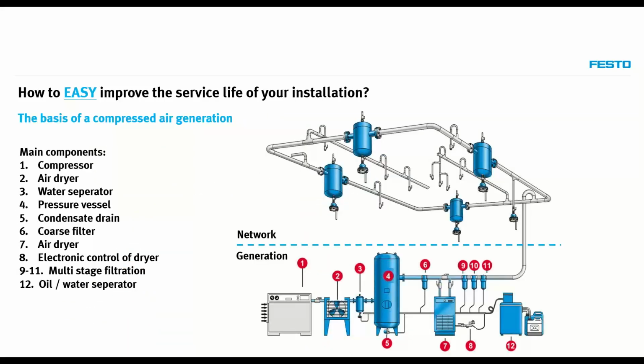So in general, what are the basic components of a compressed air system? For this, we would like to zoom out on the entire system itself, because many times people are only looking at a compressor, or only at the pressure vessel, or the air grid which is available. But at the end of the day, it's a system of connected components together with different tie-offs into a facility. This can be a water treatment plant, a chemical facility, or a food production location.